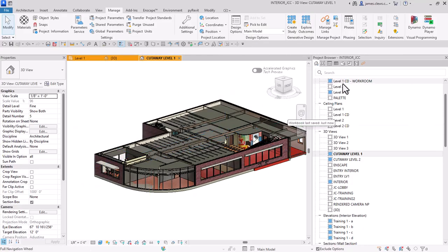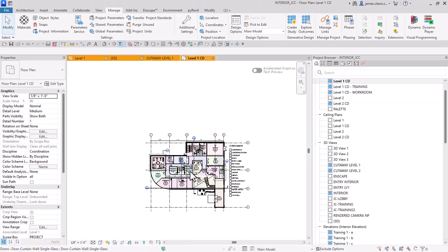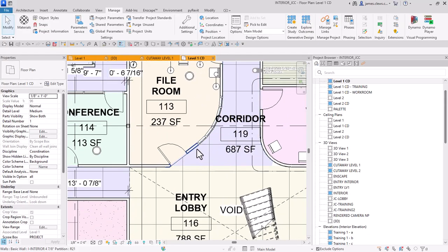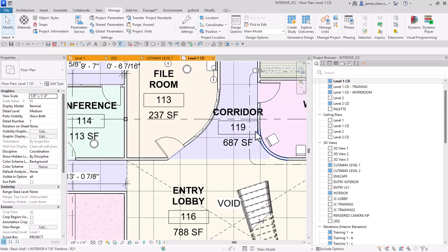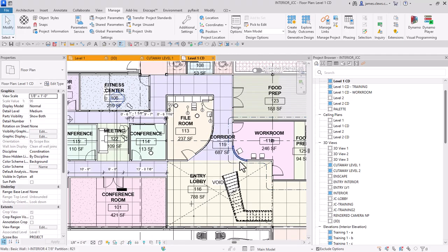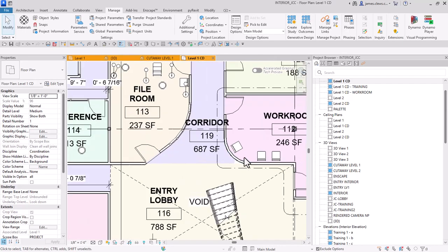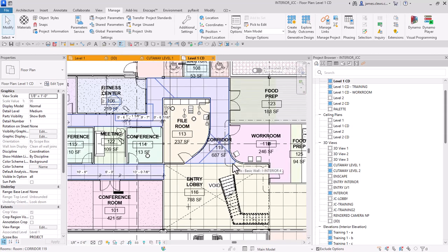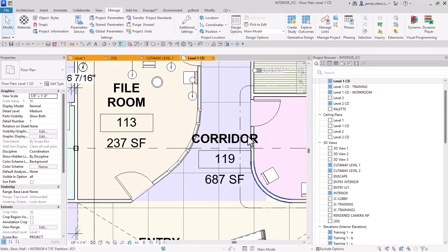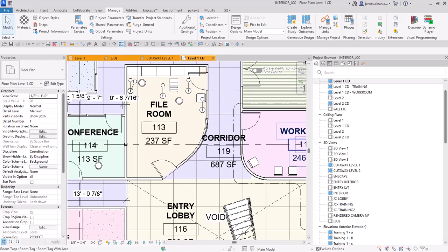I did look to see if we had in the views, did you have at least one curved curtain wall, and did you have a curved regular wall? We had looked at ways of doing that, and rather than drafting them, it was generally easier to draw the walls to a corner and then use the wall modify and specify a curve radius and pick the 2 walls and create it. Much faster than trying to draw it, because you'd have to have a wall of the same type to get the exact connection you want. So that was 5 points, and I awarded points in there.